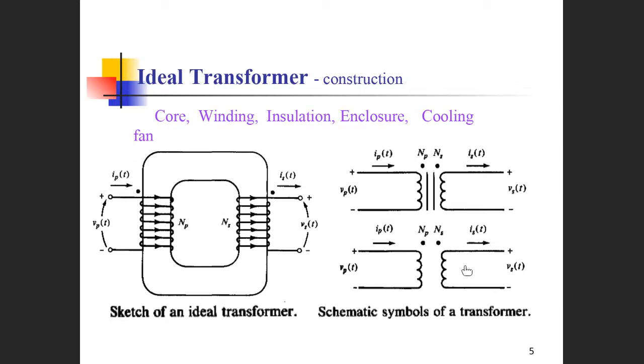When you have an electric schematic, you should tell the engineers and the workers how to connect the transformers to the polarities. So you should mark which wires should be connected to the positive side of the transformer. Of course, positive or negative here is a relative matter, because it is applied to AC systems. In AC systems, the polarities change with time, so the positive here is just a sign, relatively positive at one moment.